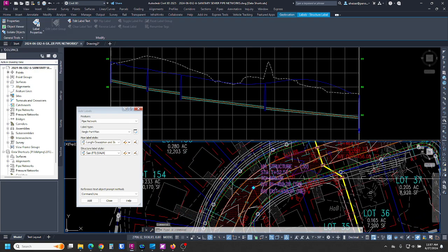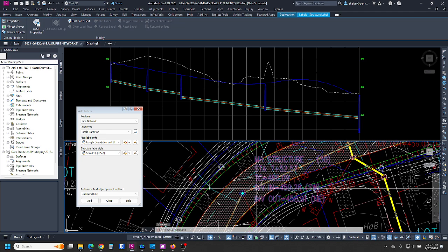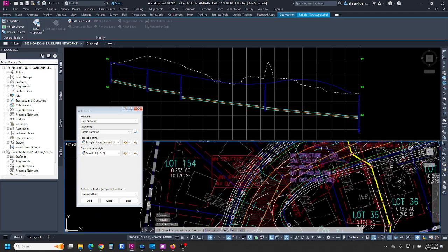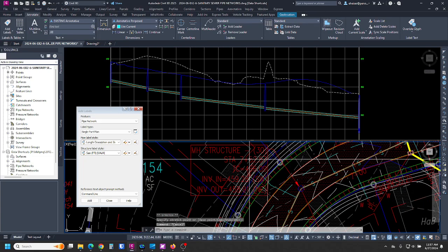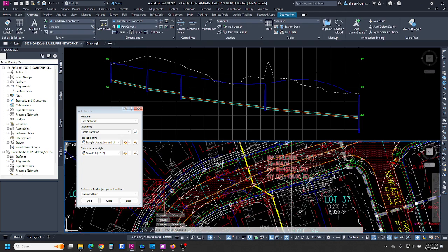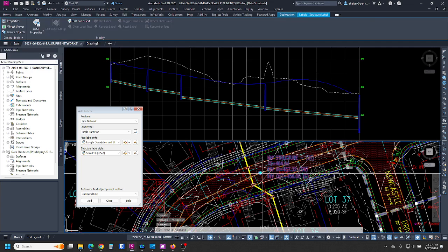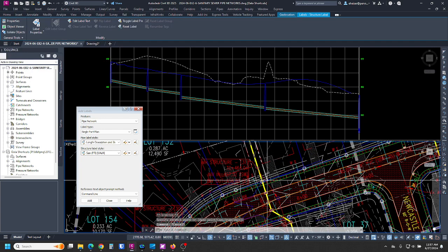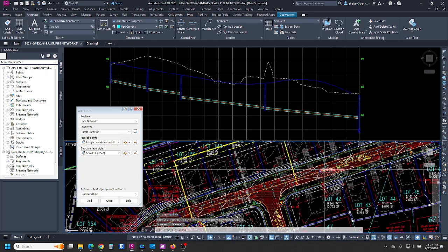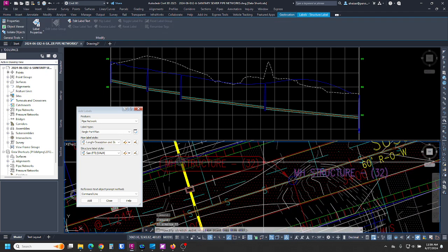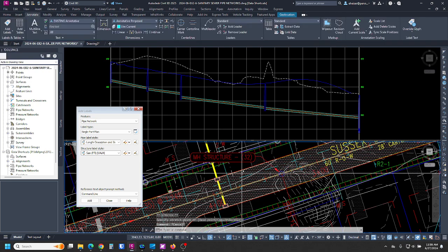So you can see on the UAJA style, it has the station of the alignment that we made for the sanitary, and it has all the same information otherwise. These labels you can click on and you can drag out to where you need them to be on your plan. The name only one puts it in an oval.